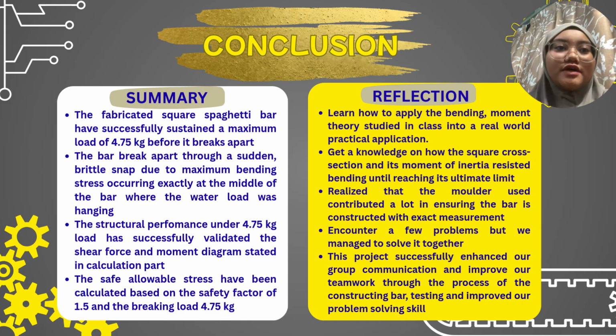Okay, so for the conclusion, we divide it into two parts, the summary and the reflection. For the summary, the first point is the fabricated square spaghetti bar successfully sustained a maximum load of 4.75 kg before it broke apart. The bar broke apart through a sudden brittle snap due to maximum bending stress occurring exactly at the middle of the bar where the water load was hanging.